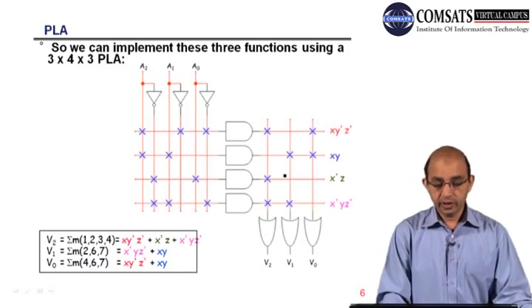But when we talk about the columns, we have to perform the OR operation. You can see that these are the switches, and those switches can be programmed. We will have this one, and this one and this one. It means x y bar z bar plus x bar z plus x bar y z bar.